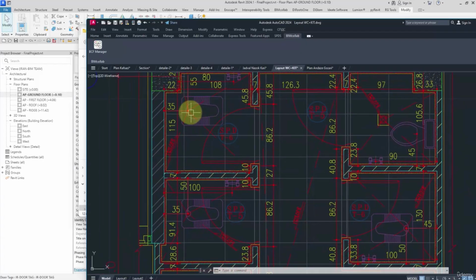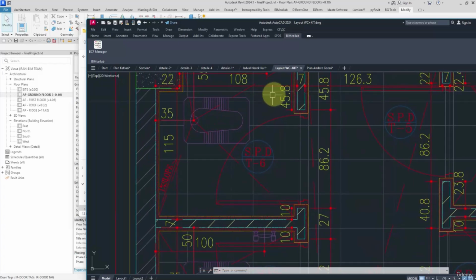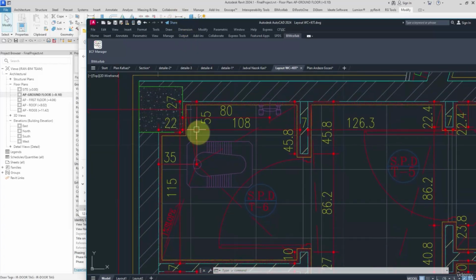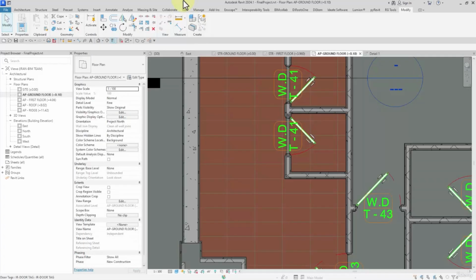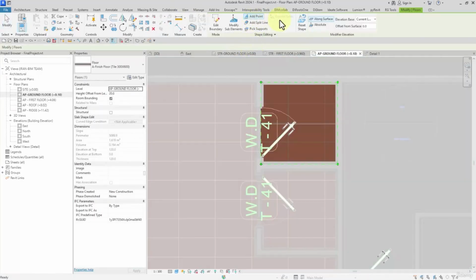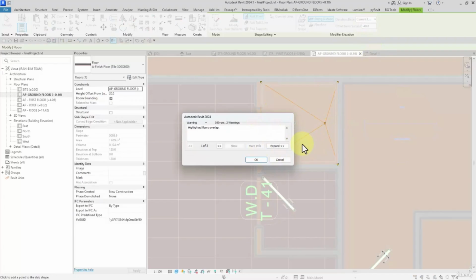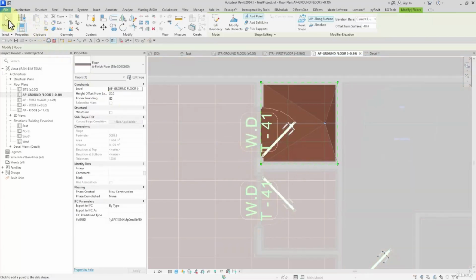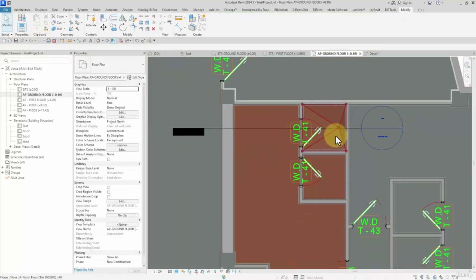here we got the floor drains and also the bathroom. Watch this. This slope has been considered. So I select it, then Add Point, offset from space -4, then I click on it to consider the slope.